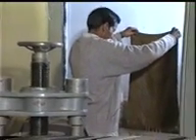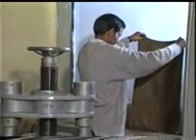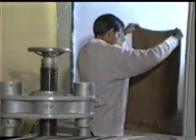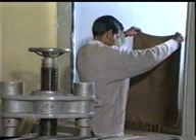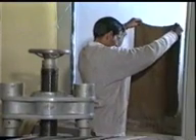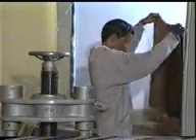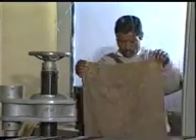After the elapse of initial setting time of cement, which is generally 30 minutes, the cubes are covered with wet gunny bag. This helps in maintaining the relative humidity of 90% and temperature control of 27 plus minus 3 degrees Celsius.